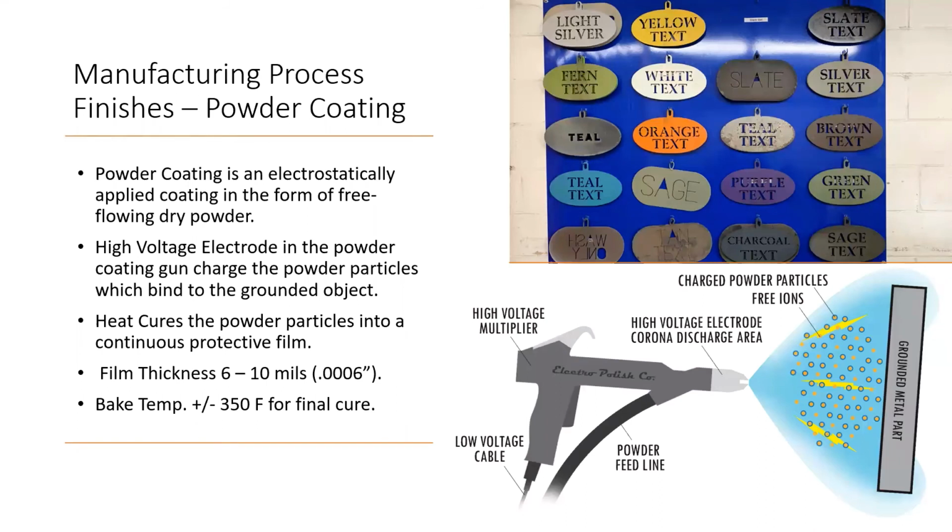So a quick review on powder coating. Powder coating is a polyester powder that's applied electrostatically, which is a fancy way of saying that it's applied using positive and negative charges. The powder itself is stored at a neutral charge in bags. Then the manufacturing line, where everything is typically hung from a conveyor belt type system, needs to be grounded, which represents the negative charge.